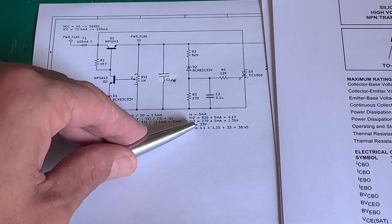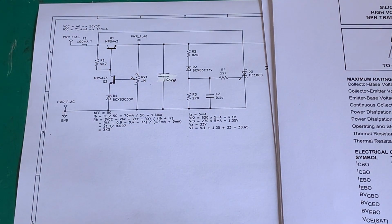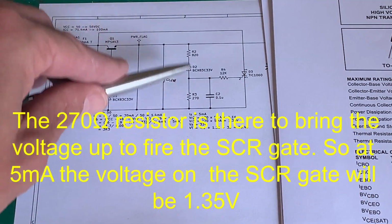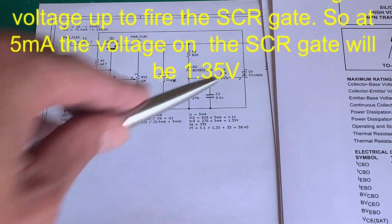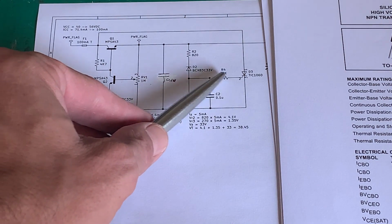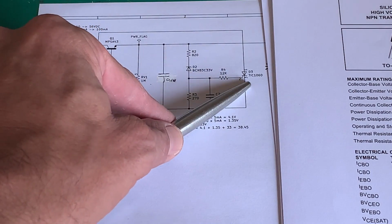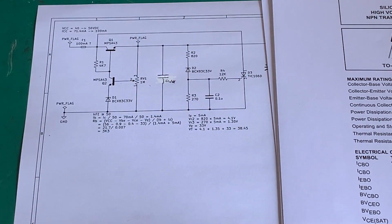And the 270 volt will give me 270 times 5 milliamp, which gives me 1.35 volts. So if I add the volt drop across the two resistors and the Zener together, my SCR will fire at 38.45 volts. And the SCR is a very simple device. I have to put a voltage on the gate and a little bit of current, and it will switch on. I can take that voltage away, and it will stay on as long as I have the holding current.